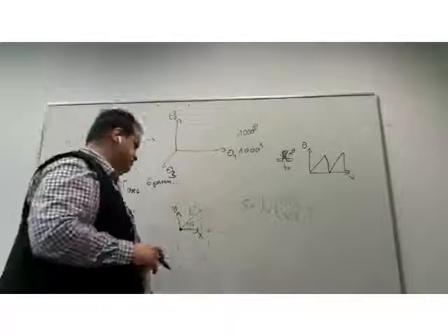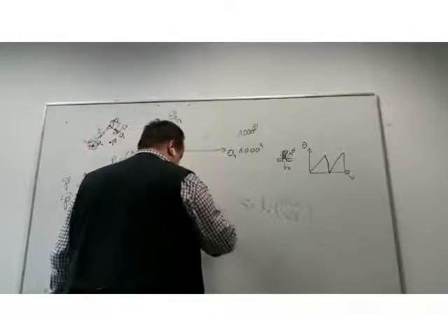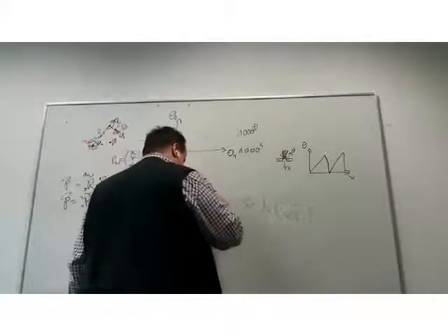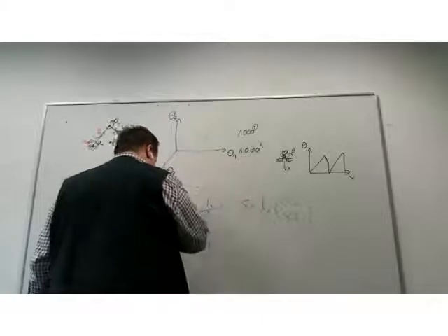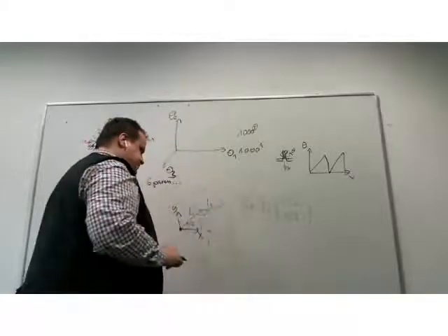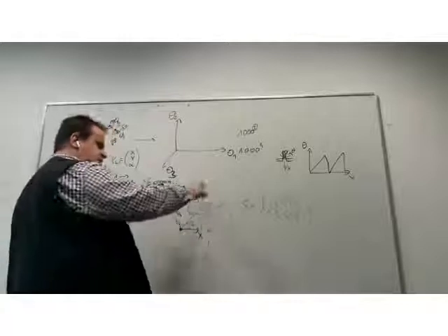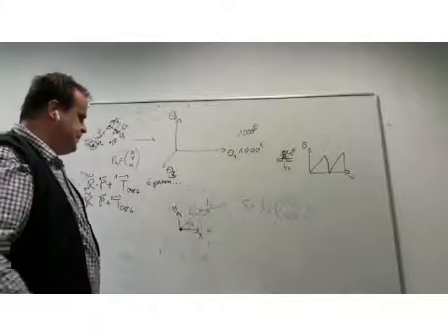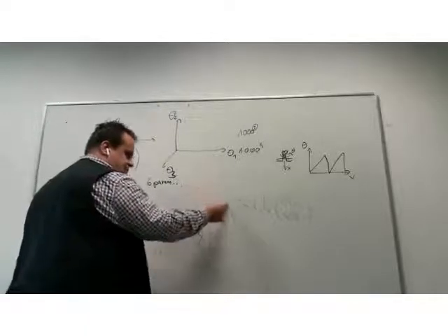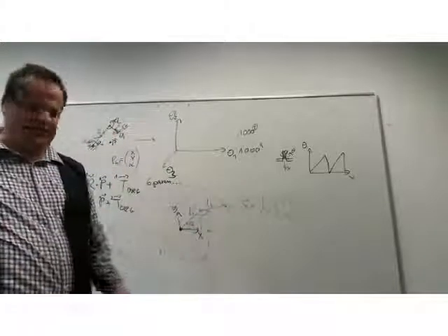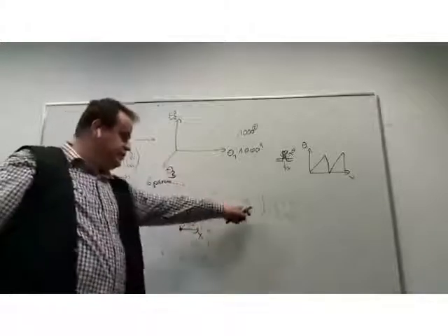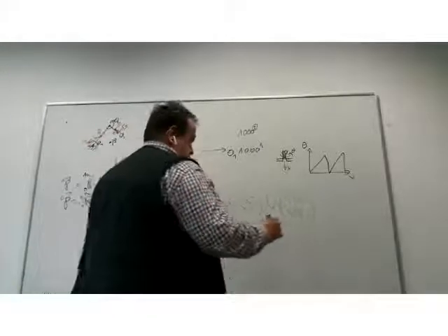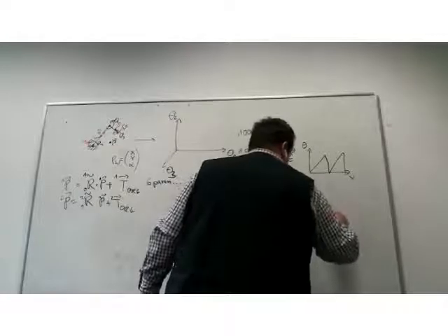Relatively easy. But I have not done the second link. And only this is actually defined in our forward kinematics. This is basically now telling me where my robot ends up being. And this would be my forward kinematics calculation, where my end vector is depending on the joint values. So I need to add L2 times.